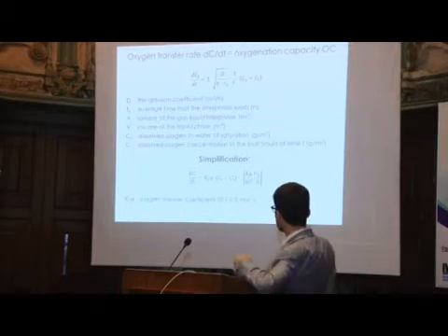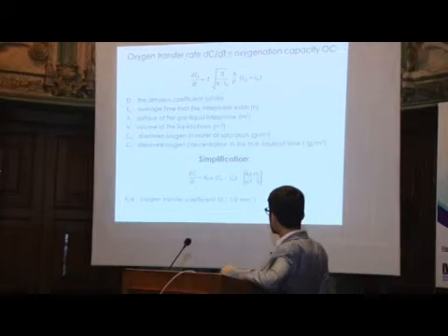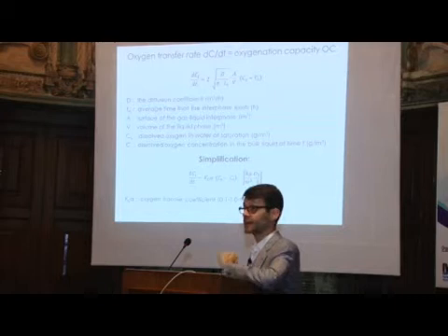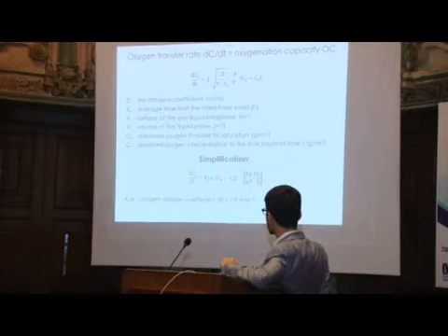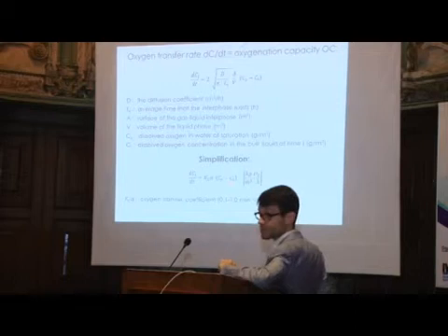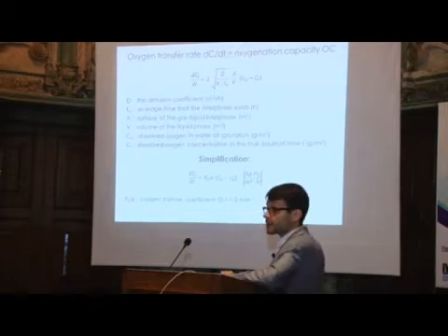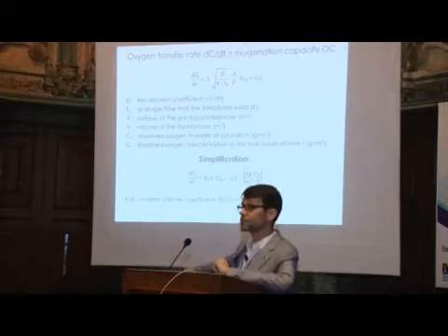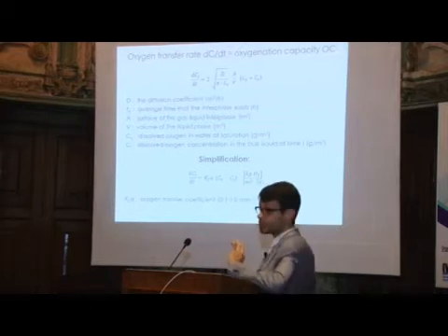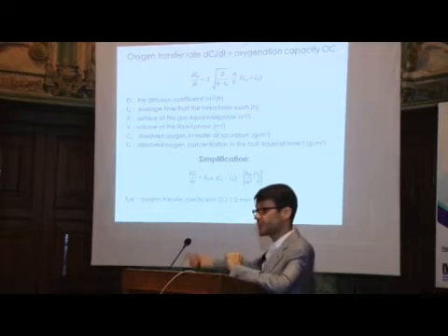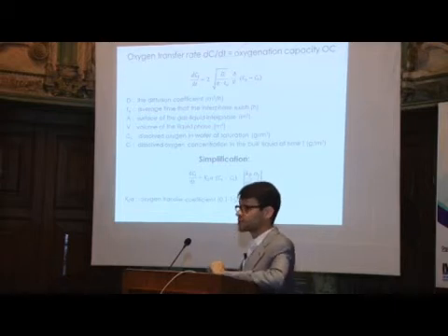So we simplify into this formula, and then you can see for a given system, ideally, of course, you have a high KLA, a high oxygen transfer coefficient, and then you have the saturated concentration of oxygen in the water and the actual one. So this is your driving force. The higher this difference, the faster you can transfer oxygen. So if you're working at very low oxygen levels, you have a big transfer and it is more energy efficient.